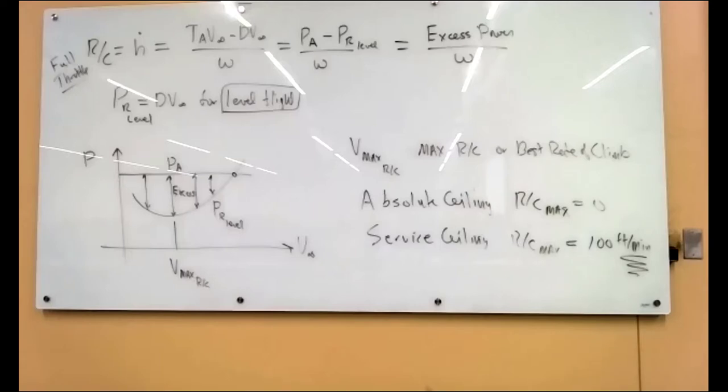You'll do the spreadsheet just like we did for the power available, power required, and then you'll calculate the rate of climb, pick off the max, and plot it versus altitude, and you're done. All right. Hopefully you've started on most of this, right? We've had the tools to do this, pretty much up to the thrust available, thrust required, power available, power required.